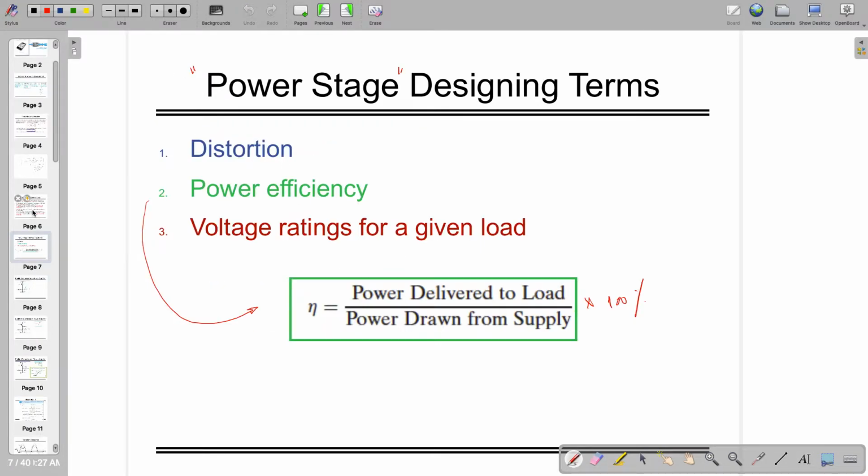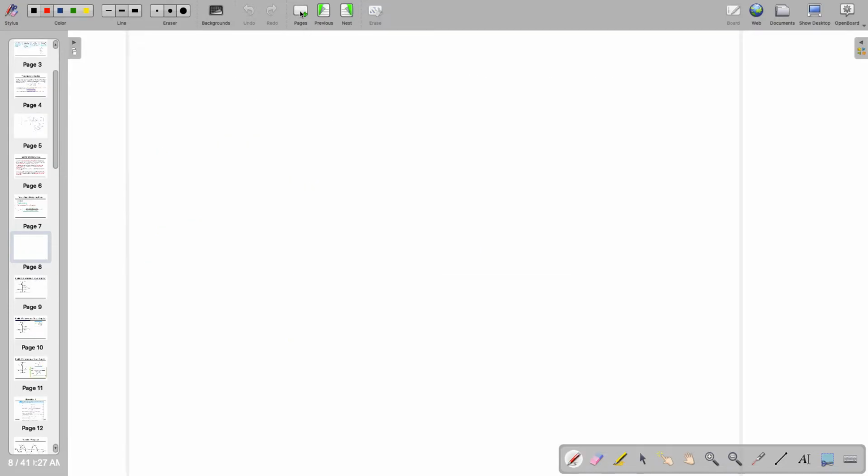So if we are talking about a circuit which can act as a voltage follower, we already studied one popular circuit, which is a common collector circuit. Similar to what we have studied in common drain. So using MOSFET, you can apply the common drain amplifier, or in the case of BJT, you have to use a common collector. This acts as a voltage follower, also called the emitter follower.